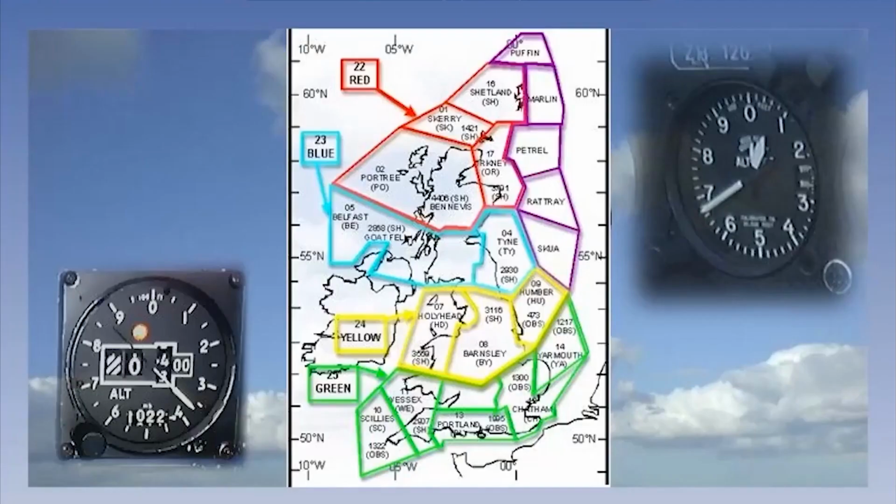The temperature error in altimetry is important and has led to a number of accidents. To prevent this, information is usually given to provide a landing pilot the necessary details to ensure more accurate calculations of obstacle clearance. Advanced instruments like radio altimeters very accurately calculate the aircraft height above the ground. Unfortunately, these instruments are only useful within 2,500 feet of the ground surface.